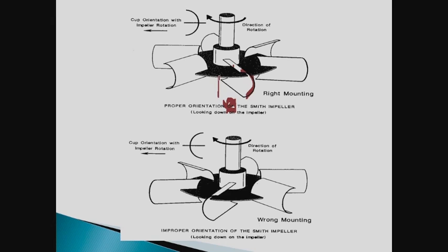Basically, it was a pipe that was cut in half and mounted on a disc. So when gas comes up from below, it hits the disc, and the impeller spreads out the gas, or disperses the gas. There's a vortices at the bottom of these blades, right? And they collect up the gas, and then they disperse the gas. So the way I draw that is, you have a vortex here and a vortex here, and some speculate if there's not a vortex in there. But anyway, you have a vortex, and this is where the dispersion happens. These two do not meet each other.